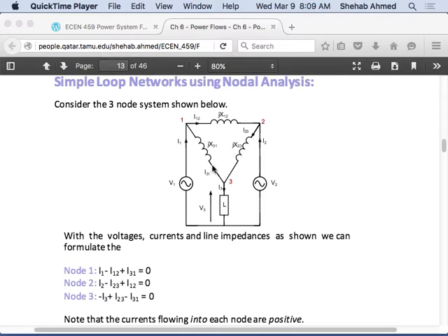But the problem we posed last time was that I can increase the voltage at node 1 and the voltage at node 3 together by 10 volts, and the difference will still be the same. If I divide that difference by the impedance, I'll still get the same current in the branch, so it's not clear what needs to be done in this case.